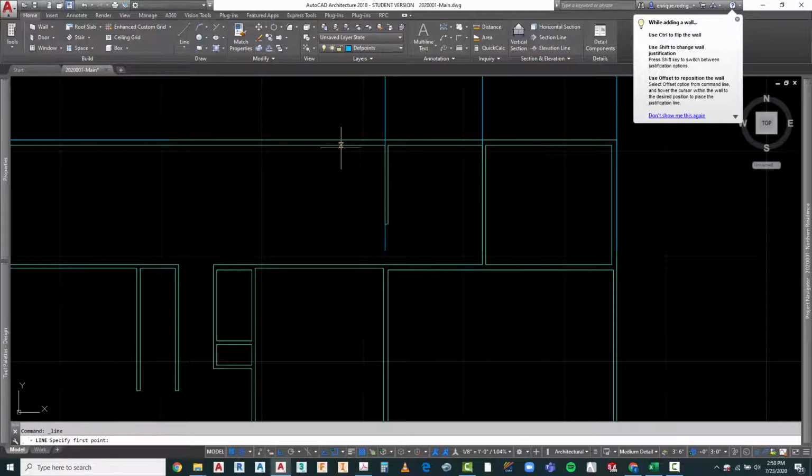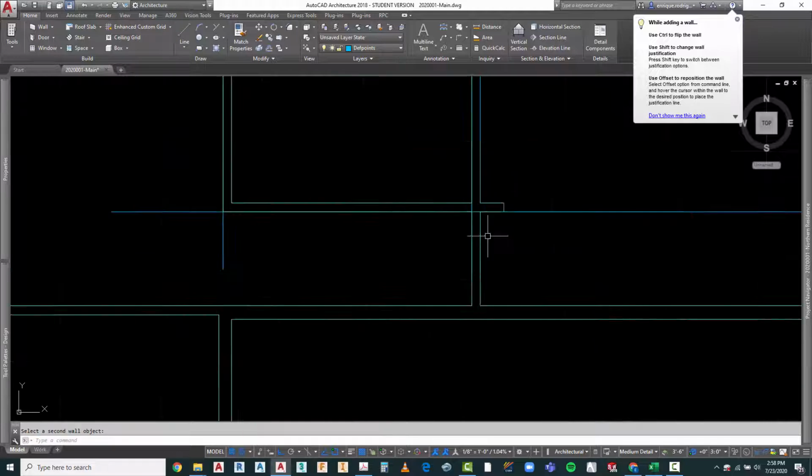So I'm going to go ahead and draw a line here. And I can move, copy, offset. I just got to make sure to delete it later on, 7 foot 10. And I'm going to take one of these 4-inch walls here and move it right to there. And I'm going to fillet these two. And I'm going to trim this one out.